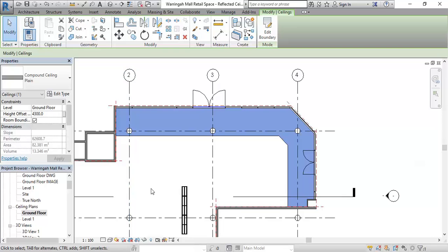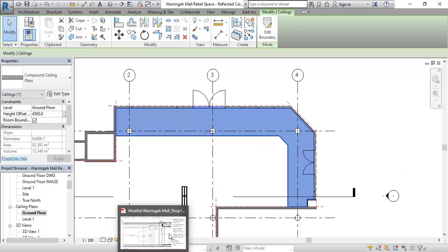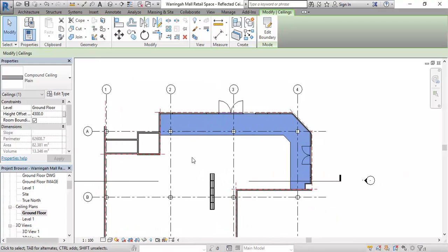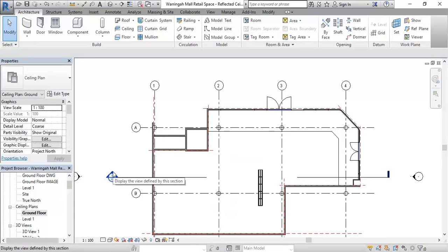Yeah, it says COS. Do you know what COS means when you see that in a dimension? Exactly, yeah, check on site. Yeah, that's it. So when you see it, you can just use that dimension because I'm assuming you won't need to go and check anything on site. So that should make it easier.